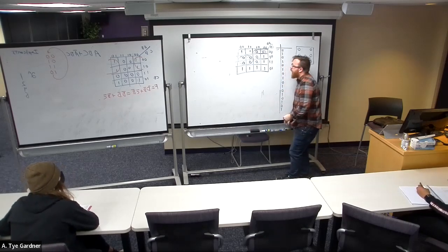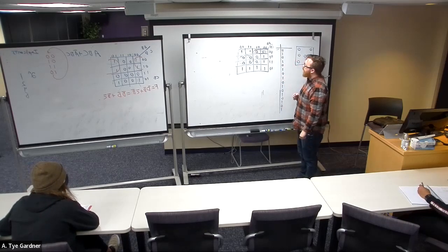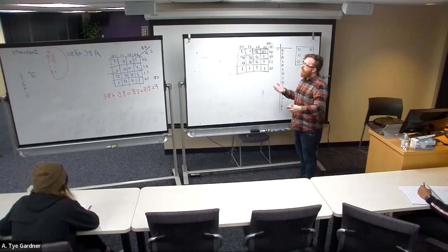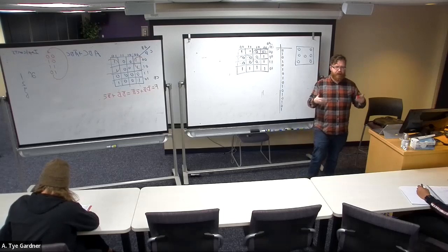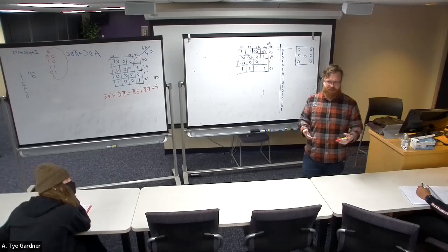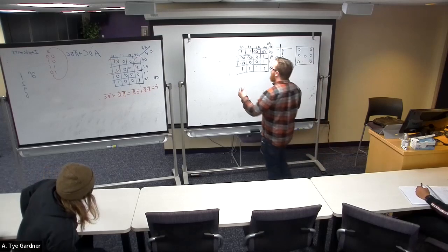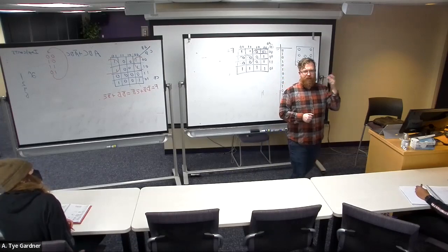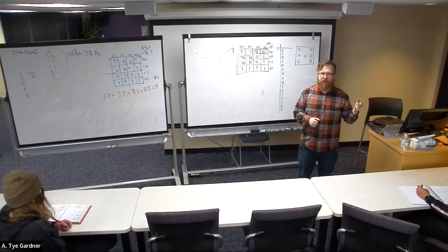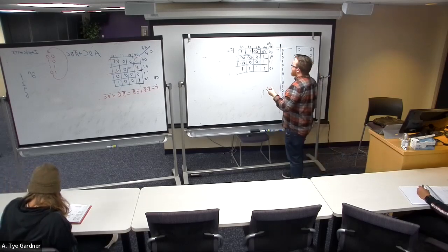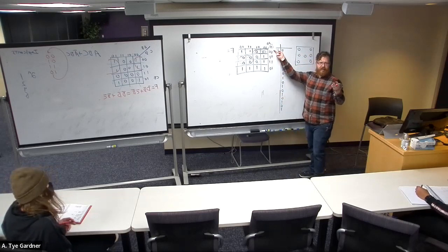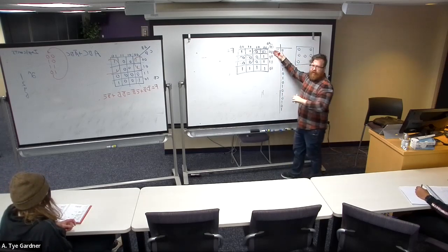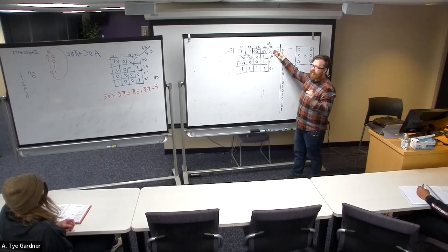And now I have to write the expression for this circuit. I've circled it, I got coverage. But the next step is different from the sum of products because I'm generating a product of sums circuit. I've already alluded to that. And so it's going to be written as a product of sums. However, we're still going to start with what doesn't change. Let's start with this one. He's actually a little easier to see because he's self-contained. A doesn't change, C doesn't change, D doesn't change. So I have not A, not C, not D.